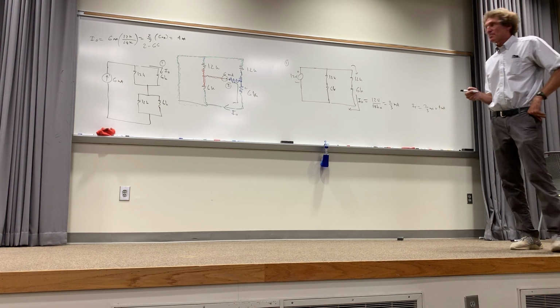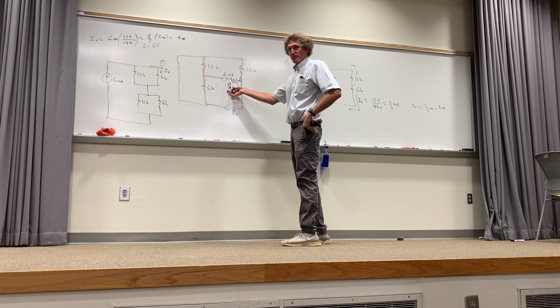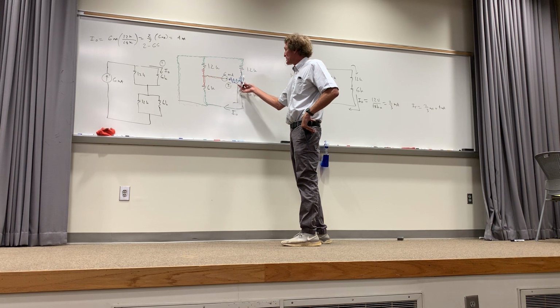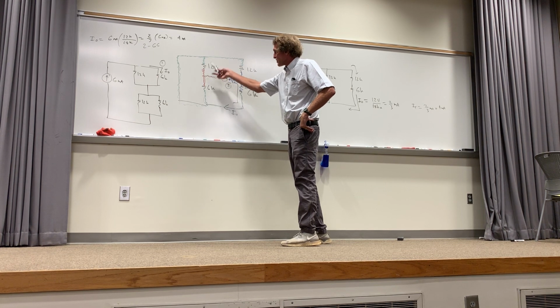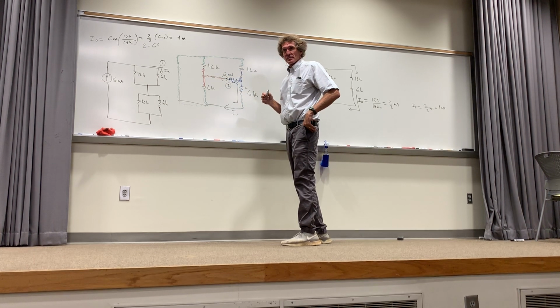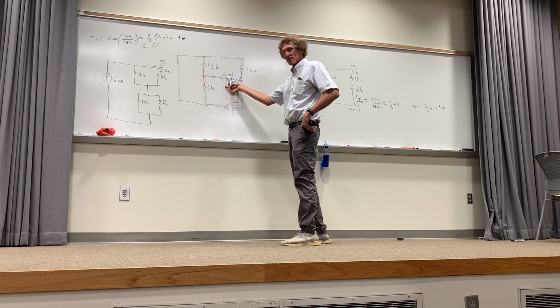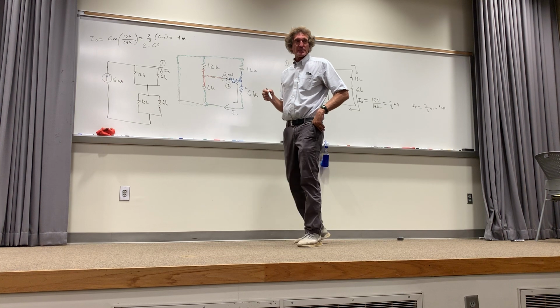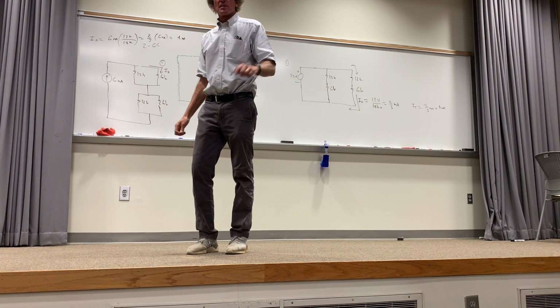It's just analysis. The hard part of this one is this redraw right here. All right, follow me, it's the redraw. Work on that and you'll see it. And the colored markers, trust me, help. They help a great deal. Everything between the colors, I mean between the blue and the green, and between the green and the red are in parallel. All right? You start, the blue starts off the 6 milliamps, the red returns to 6 milliamps. You go through it and see. I hope this answers your question. Other questions? That's a good one. Other questions?